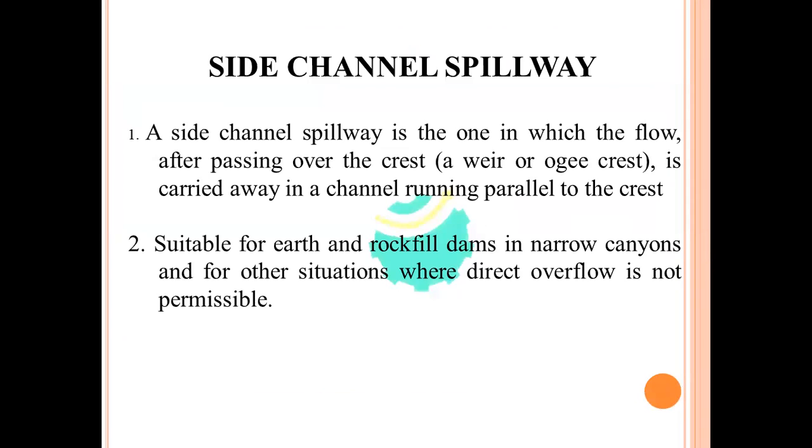Next important one is the side channel spillway. A side channel spillway is one in which the flow, after passing over the crest, is carried away in a channel running parallel to the crest. The name itself represents it: it's a side channel.